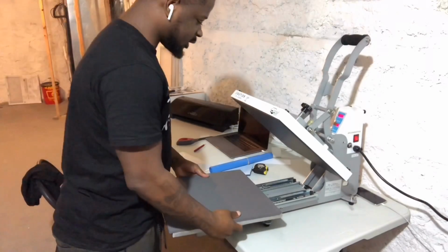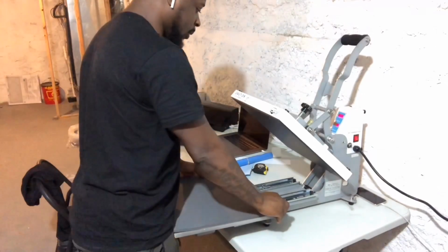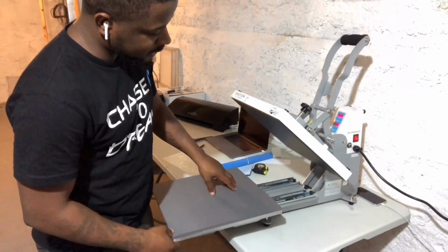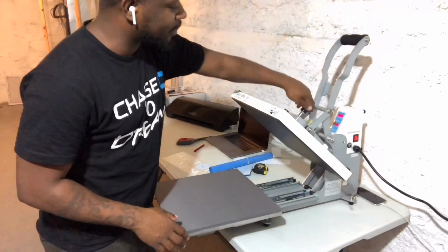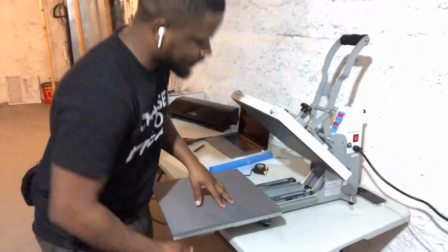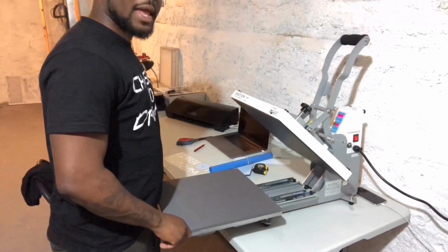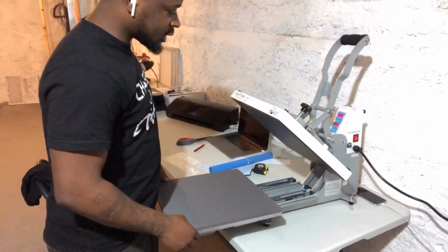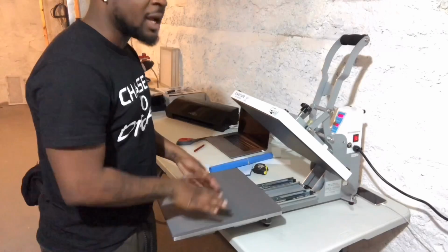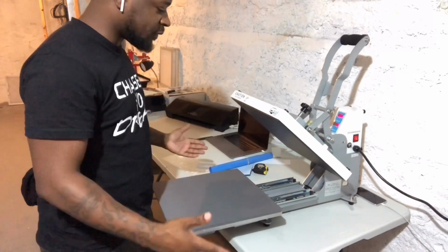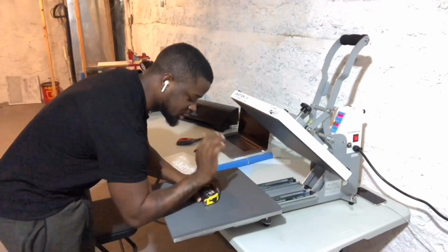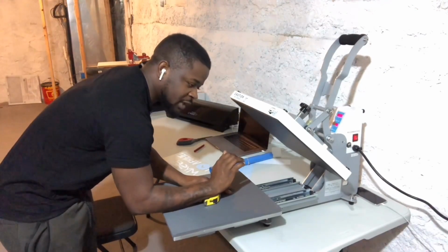All right, now I'm gonna address something real quick that some people have said about the press. So one of the things that happens is, on a heat press, usually either the top platen or the lower platen has some float to it, right? Now you can tighten this up, but what ends up happening is if you're doing any other type of substrate, you want this float so that it can get a clean seal, and that's why they say swing away presses are better for sublimation, because they always have a flat seal on whatever surface you're pressing on. However, if I was pressing this, and it goes to close down on it, it won't close fully if one of these doesn't float.